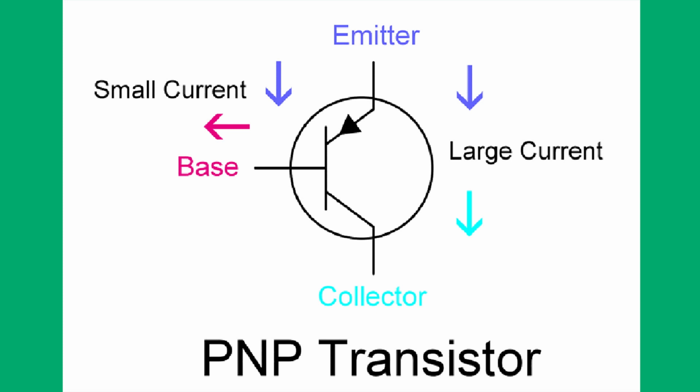This represents the flow in a push-pull circuit, where the positive half of the waveform would be passed through the NPN transistor, and the negative portion of the waveform would be passed through the PNP transistor. A voltage difference of at least 0.7 volts between the base and the collector for NPN and between the base and emitter for PNP is necessary for current to flow. These two diagrams are of bipolar transistors, which are called bipolar junction transistors. FETs will be discussed next.